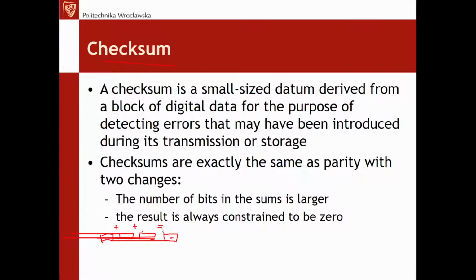What we do during the reception, when we receive the data, is this: we receive 4 bytes of data, because the frame is composed, in our example, of 4 bytes. With the checksum, we add those 4 bytes together and check if the final result is 0.